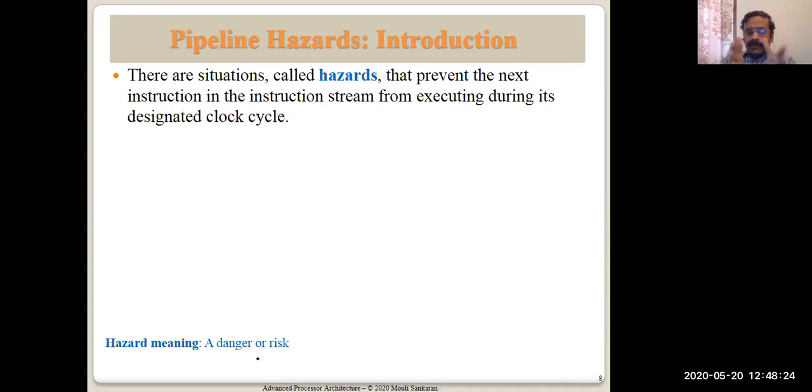Similarly, we are expecting the CPU to perform instruction execution such that every cycle it changes the instruction it is doing. You tell one part of the hardware to execute part of an instruction, and then in the next cycle do something else, whereas some other part of the hardware is processing something else. So you are splitting the execution of an instruction into multiple stages. So it has its own problems. Let me explain what those problems are now.